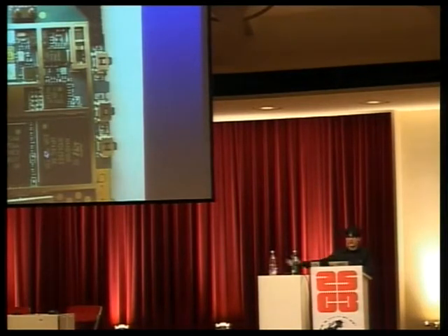And if you think, oh, this is an HSDPA modem, but if you try to think what that device does, it's actually a miracle. This is something that can receive and transmit on 7 different frequency bands, right? You have quad-band GSM plus tri-band 3G. And it speaks, what is it, like 3 or 4 different modulation schemes on those frequencies. It has power amplifiers for different bands and so on. So it's actually quite a lot of technology in there.